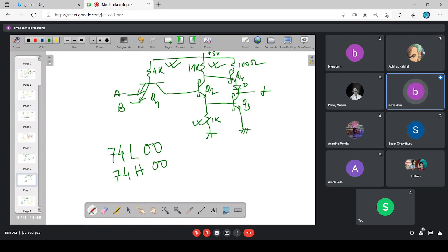But if I go for increasing the resistance values, as I have earlier seen, the propagation delay will be compromised; the propagation delay will be worse. But now, to improve the propagation delay, we have replaced the switching devices by Schottky transistors. So by introducing Schottky transistors, I have improved the propagation delay, and at the same time, by increasing the resistances, I am improving the power handling capability of the TTL gate.